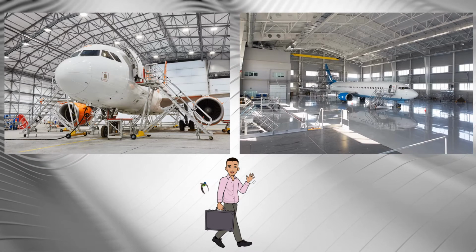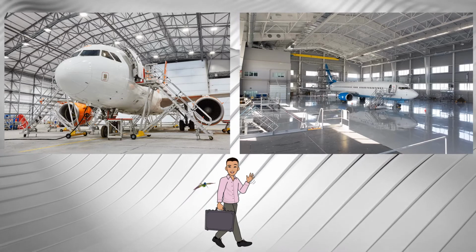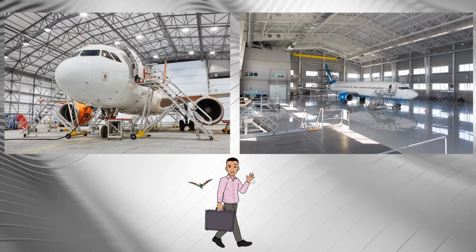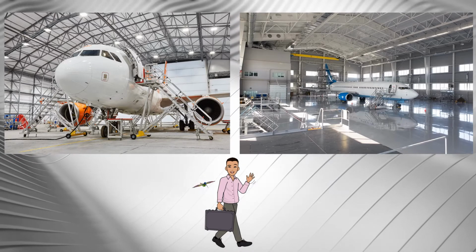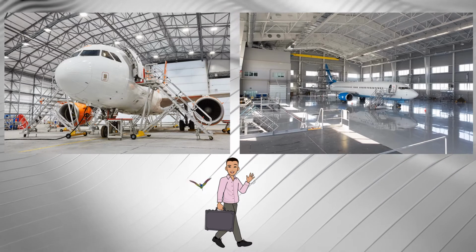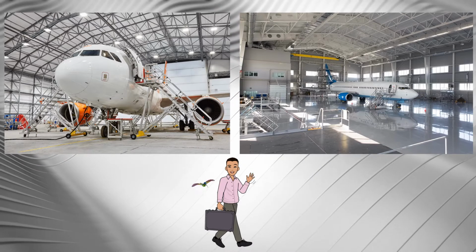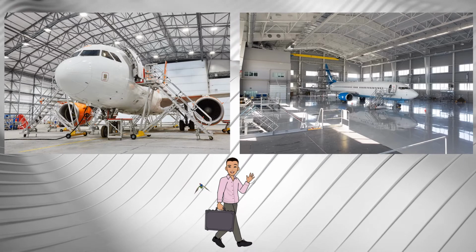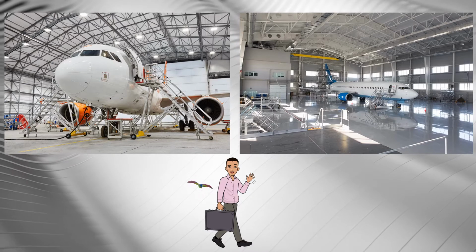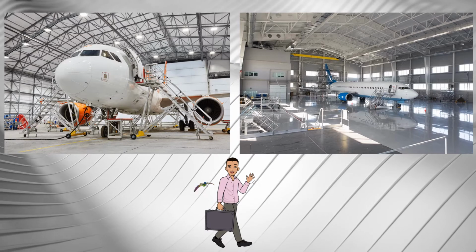Electric power, air, and other services may be from roof-mounted motorized rails or in the floor. Heating is by embedded floor coils or high-power blower suspended from the floor. Blowers are large units appropriate to the height of the hangar. Sprinklers may be installed depending on the extent of the maintenance carried out and the safety procedure adopted regarding onboard fuel. Except for roof maintenance, the maintenance requirements for a hangar are usually slight,